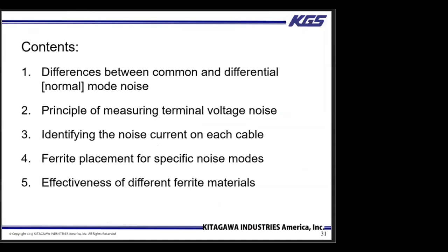Inverters are used in various devices. As devices become smaller, they are designed with higher performance and energy saving features. Noise generated from inverters can radiate from the device and cause malfunctions. First, we will review common and normal mode noise routes and the terminal voltage. Then we will show you the noise current that can be identified by visualizing it using a current probe in order to help you assess the concept of the noise current.